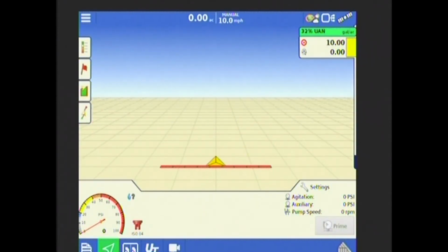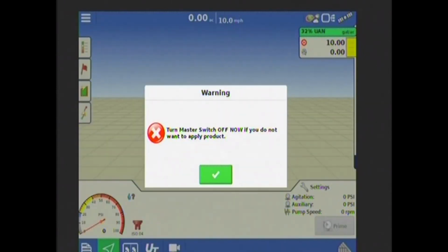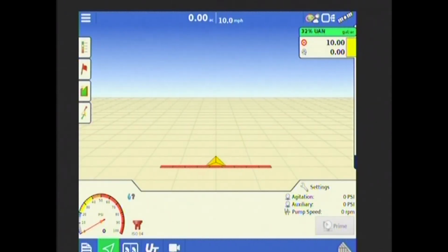One thing to note down here in the very bottom right hand corner, I've got a couple of lines, some vertical, some kind of going at a diagonal. This is where I can turn auto swath on or off. Auto swath is Ag Leader's swath control or section control system. Tapping on that will make them green. Tapping again will make them gray or turned off.